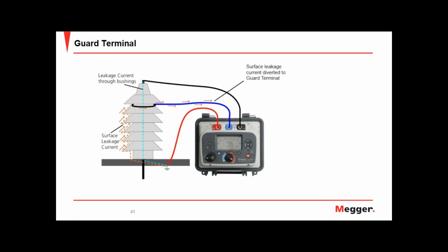Now there is some controversy. Some people seem to think that an IR test will actually damage a cable, especially if it's an XLPE. And there are certain circumstances where an IR test is not the preferred means, and a VLF, or very low frequency, test may be the preferred method. But in most instances and for most assets, the IR tester is still the go-to tool.